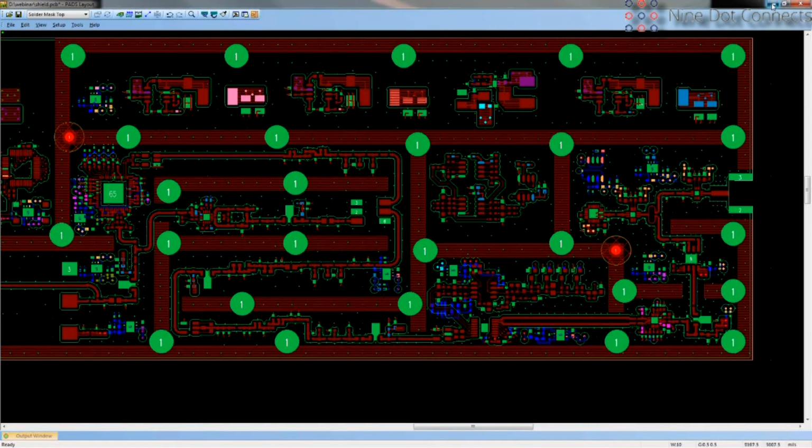Okay, I'll move this down. This is a back drilled via, and it's something that most people are not familiar with. So let's say that you've got components on both sides of your board. This is a depiction for an 8-layer board. You've got an RF line that you're trying to get from the top of the board down to, let's say, layer 3. And then it continues on from there to get to a different part of your board.